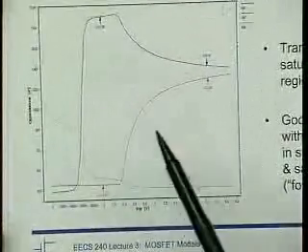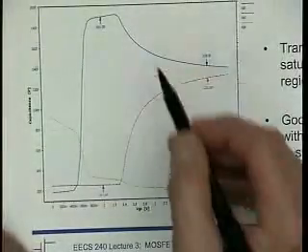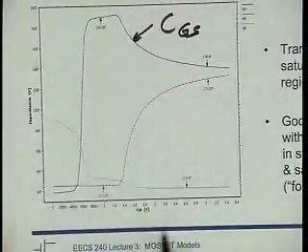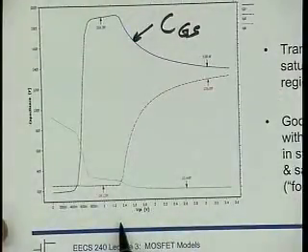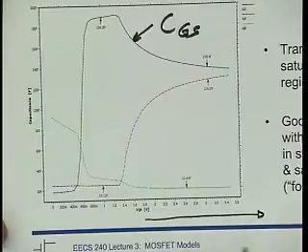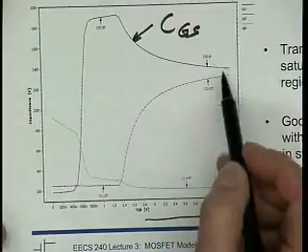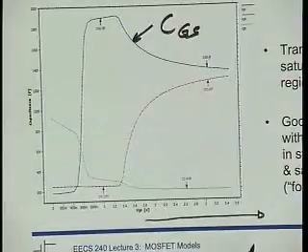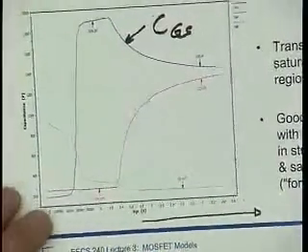So here is, for example, the CGS, and here I vary VGS again, and I made it so that here I run into saturation. So here really I get this 2/3 of WLC ox and so on. So you can verify this.